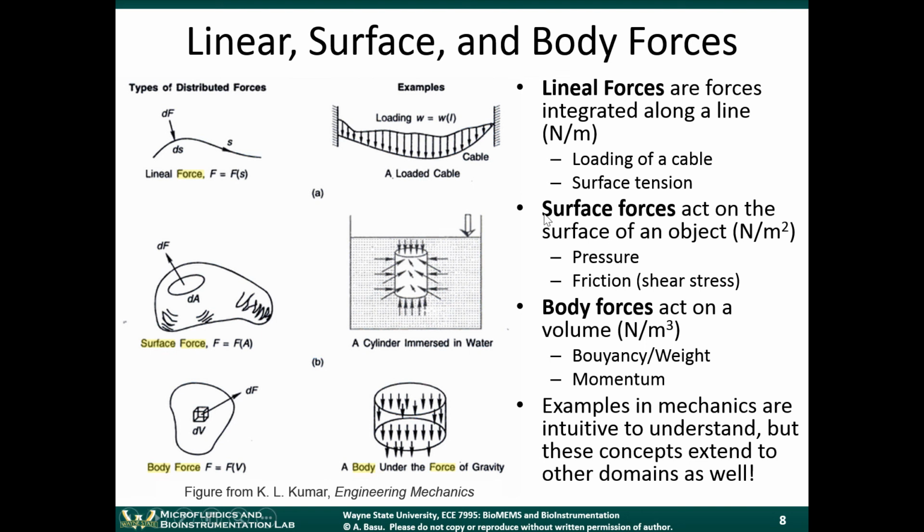Now I'm ending with the lineal forces because these are, I would say, the least intuitive of the three. But there is such a thing as line forces too. The body forces scale as length cubed, surface forces scale as length squared, lineal forces scale as the length. An example of a lineal force would be a cable under tension. Let's say you have just a line cable, and you have something hanging from it.